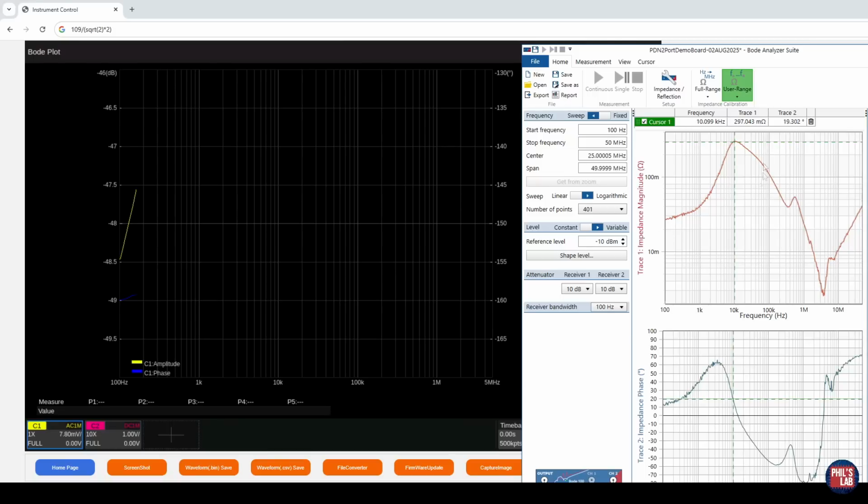What should happen is that we get the same kind of curve shape using our Bode plot tool on the left-hand side as we did using the vector network analyzer. We're doing a very, very similar measurement where we're measuring the output voltage noise generated by our current draws.